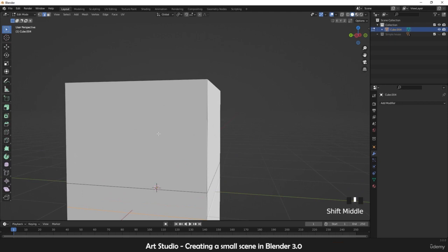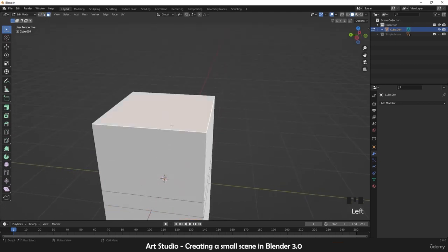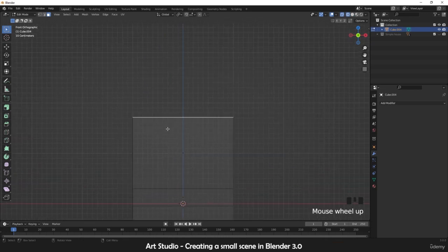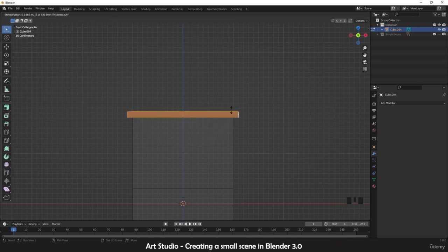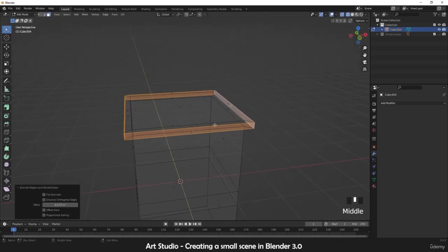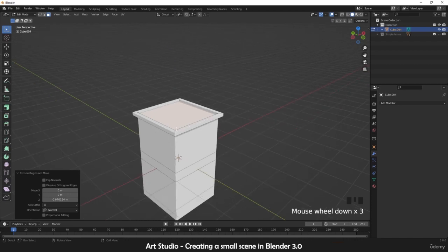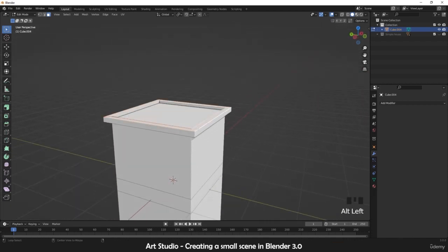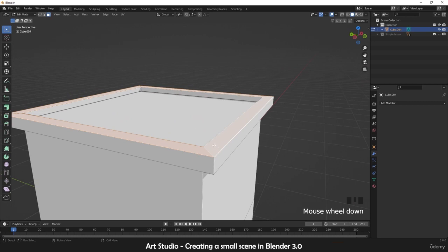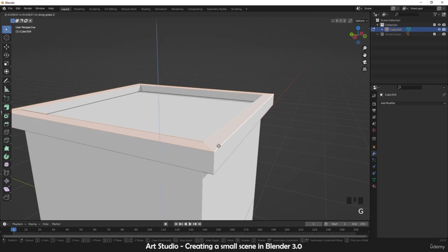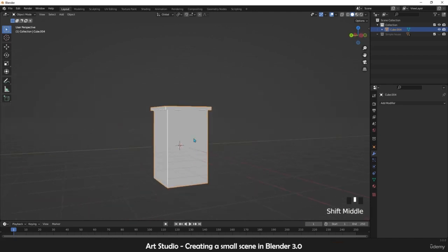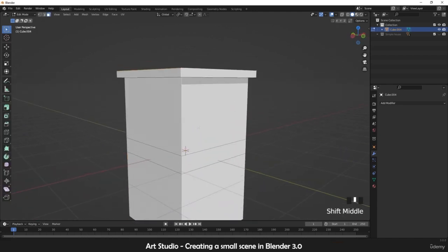So now I actually want to make the ceiling first, the roof first. So we go here and I just select E, extrude, and holding down Alt and Alt E, face along the normal. And again we select this face right here and E for extrude inside. So that's it. And even we can select this by holding Alt, we are in face mode, G, Z. So that's it. Now I want to make some window right here.